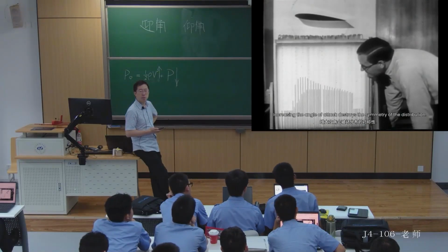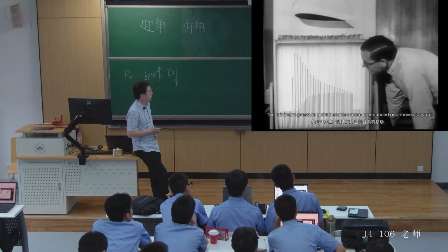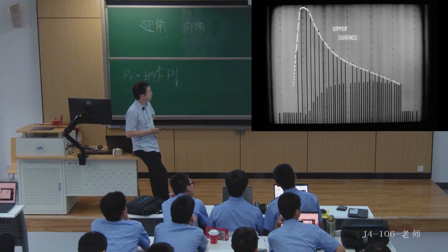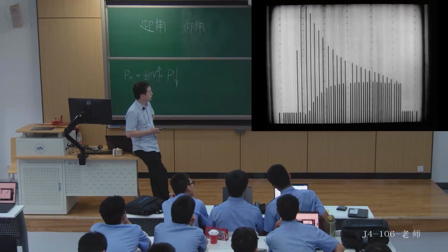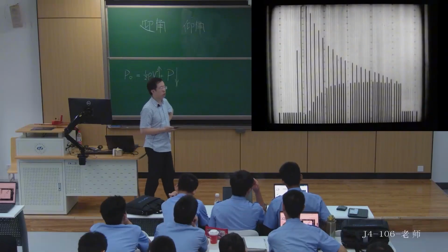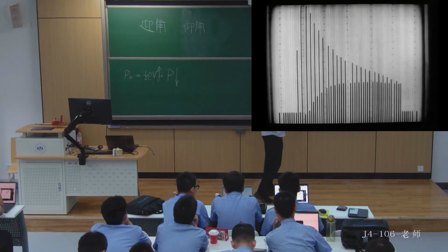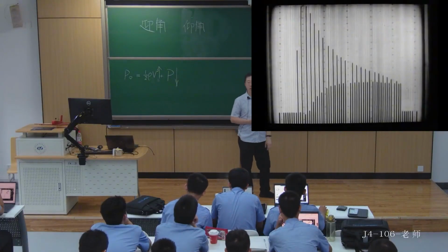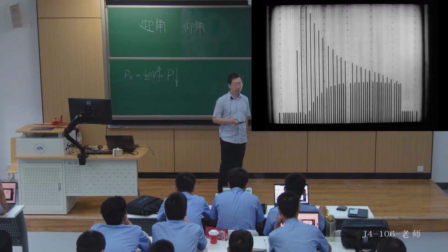Increasing the angle of attack breaks this symmetry in the pressure distribution. The point of minimum pressure becomes more pronounced and shifts forward, increasing the severity of the adverse pressure gradient. Alright, so this is the entire process of the experiment. At this point, we can use the liquid column to understand the local pressure, right? From this, we can determine how the lift changes. As for how to interpret this graph, we'll explain it to you in detail a bit later.